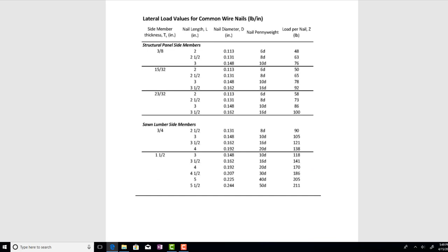This particular diagram or table, if you recall, is for load capacity. I often will use the bottom part of the chart if I'm attaching a 1 by something or a 2 by something. Then we can determine which part of the table we need to utilize. Then we usually define it by the size of the nail. And so if I'm attaching a 1 by 4 with 10 penny nails, then there's my load carrying capacity.